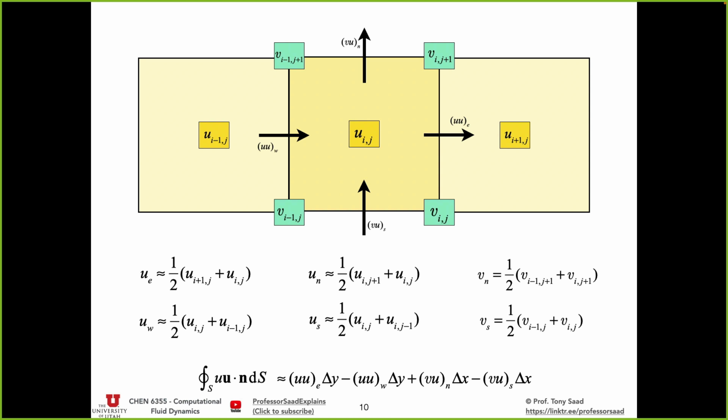Perfect. So now compare that to the finite difference method. They are quite different. There's no comparison anymore. The staggering alone just changed everything. But it made things more compact, closer to each other. We're always close to those control volumes. So now let's do the y momentum. Really, the convective flux is the hardest one, so that's why I started with it.